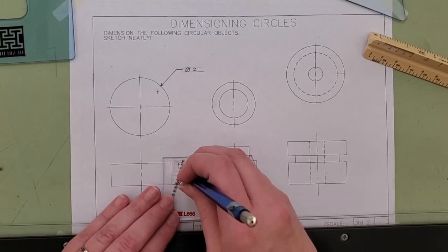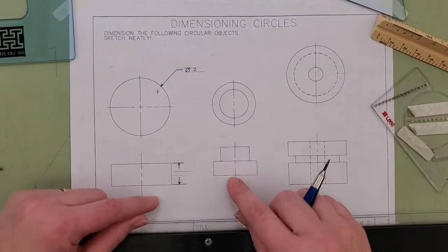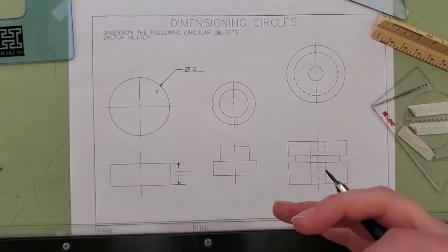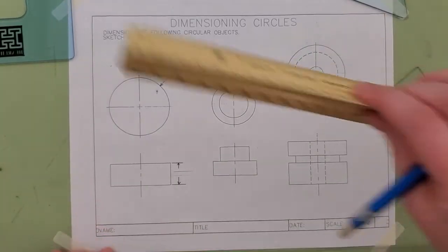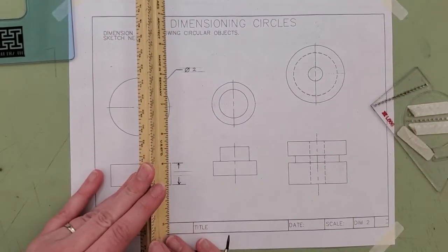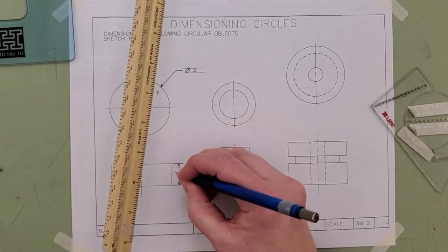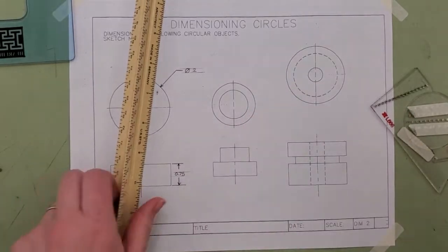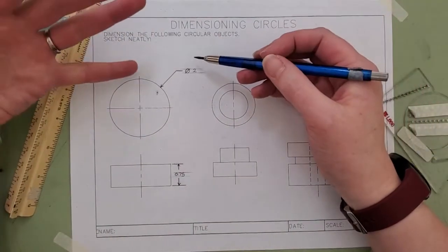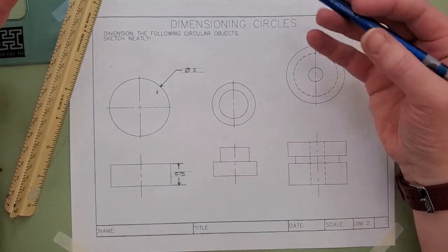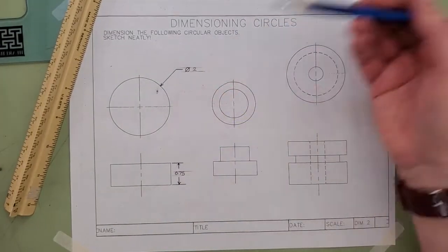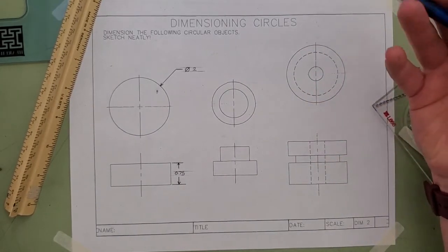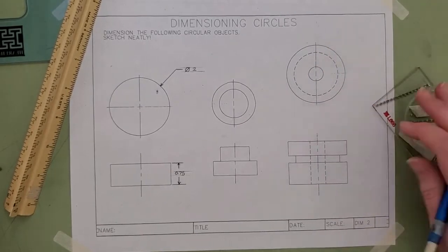And this should be construction weight lines, guys. Okay, I draw mine dark right now because I want to make sure that you can see it, but it should be construction weight. So light that I should have to lean forward and squint. But that total height is 3/4, so that would be 0.75. Okay, so the thing is, you're going to want to make sure that you're giving all the major dimensions, the total height, total width, total depth, which is easy with a hockey puck. But as you're getting to the cylinders that have multiple layers to them, then you're going to have to start making sure that you're counting lines and so forth.